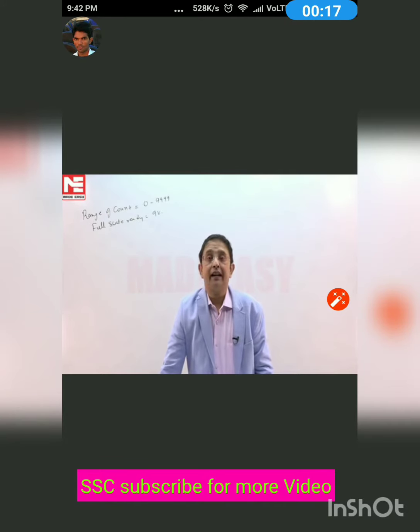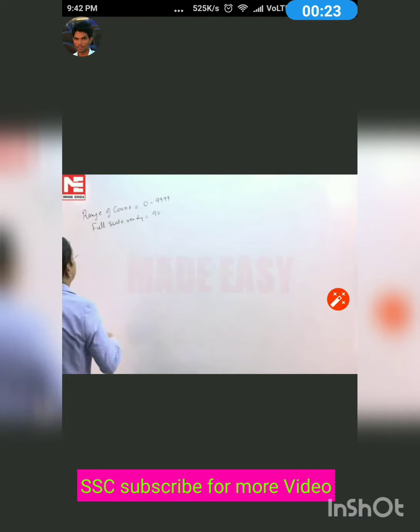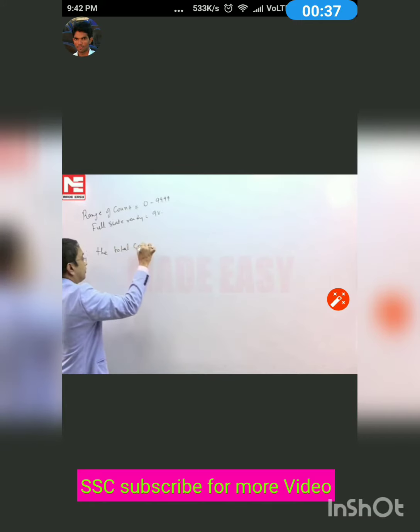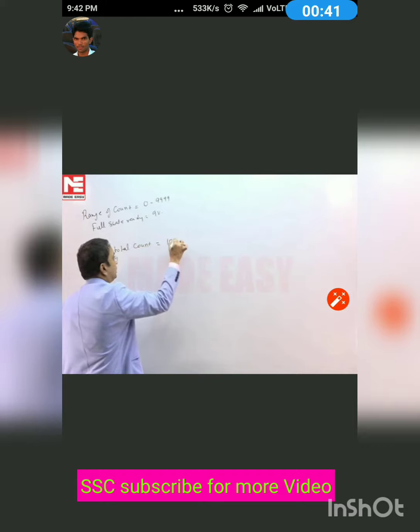Resolution is the full-scale voltage that the voltmeter can measure divided by the total counts. The total counts in this case can be written as from 0 to 9,999, so this voltmeter will have 10,000 counts. Therefore, the total count is going to be equal to 10,000.